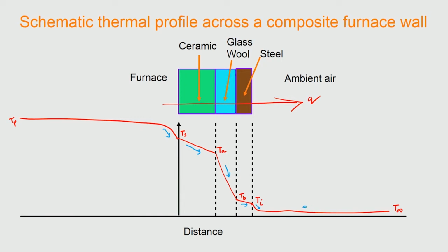Okay. So this is how the heat flow is happening, and if it is steady state, then the slopes have to be adjusted according to the thermal conductivities for the respective shells. Okay, so when we now want to write expressions for each of these, we already know that for this first expression you write H into Tp minus Ts. Okay, here the last one it will be H. So this is inside, this is for outside, into Ti minus T infinity and so on. So if you write those expressions, they would look like that.